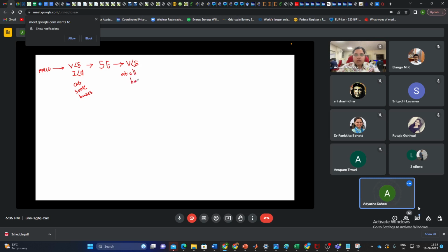Okay, so let's say you have a system like this where you had PMUs at these locations only. So you got the voltage, magnitude, and angle at only these two buses. So using state estimation, you got the voltage, magnitude, and angle at each and every bus. Okay, everywhere.